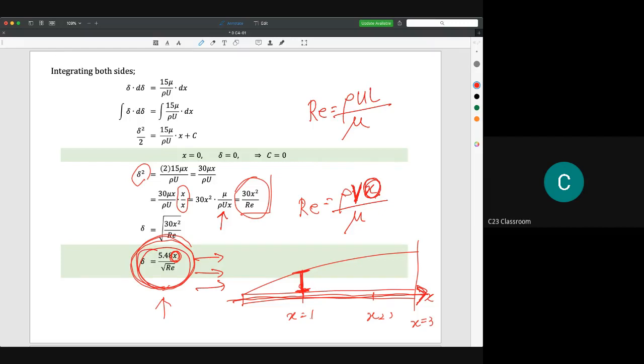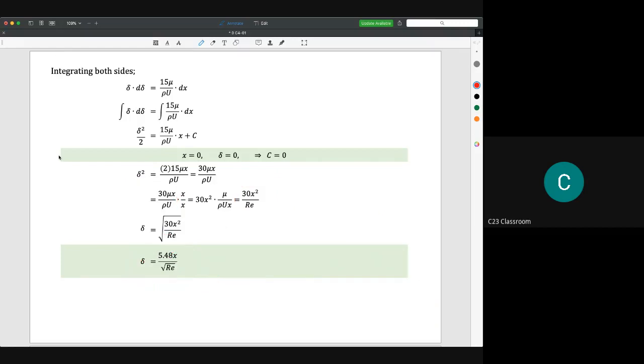And the delta here is a physical value. So that means if you are able to conduct an experiment for the boundary layer, you could measure it. The simple way is, there are a lot of methods of visualization. One of them we call Schlieren or something like that.